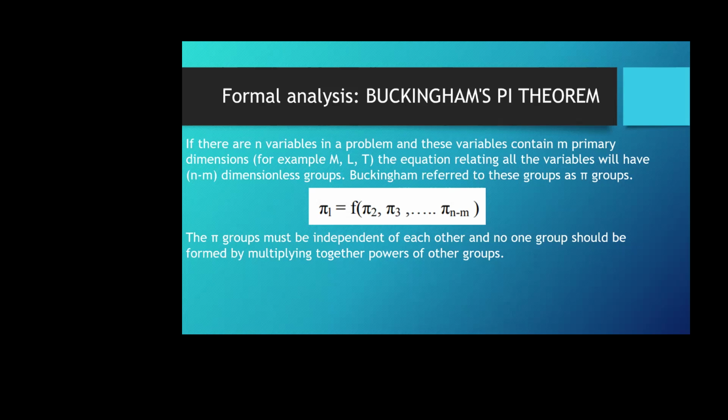In the Rayleigh method, you take the unit here and you put coefficients. If you don't know the functional dependence, then you have to put n here. Let's put n1 here, because I don't know what the power is here. n2 here, n3 here, n4 here.